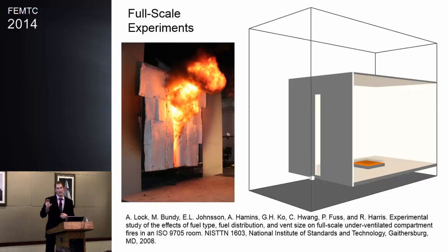So we keep the same CO2 finite rate mechanism, but now we've changed fuels on that first side. For all the different fuels, we still say that fuel plus oxygen goes to CO and H2O, and then allow the CO2 CO finite rate mechanism to drive the CO concentrations in terms of what we're seeing.